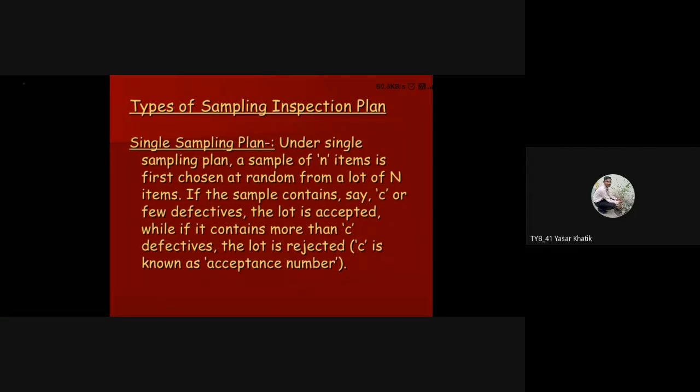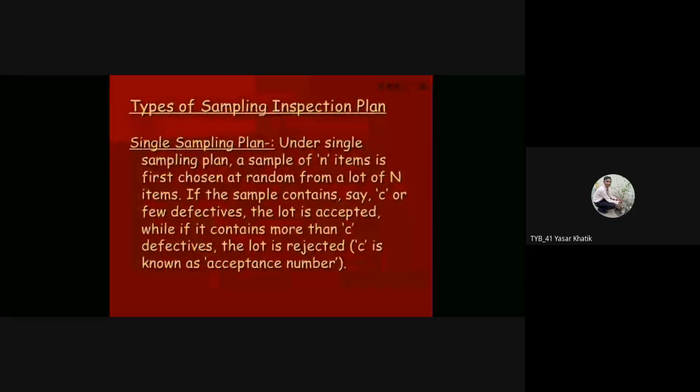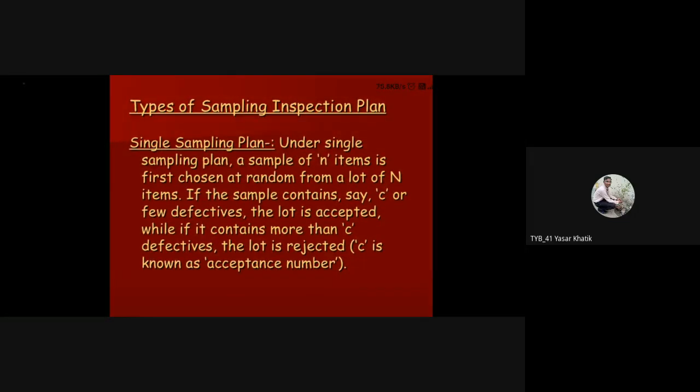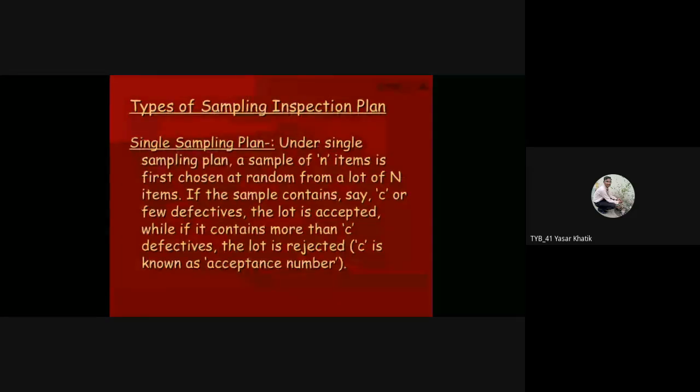It is not possible to check each and every product, so we take a sampling method. We can take some 10 or 20 products out of the 100 and check them, and based on that sampling inspection we can decide whether the lot is to be accepted or rejected. So for that we use acceptance sampling. In that sampling we have to take different product and